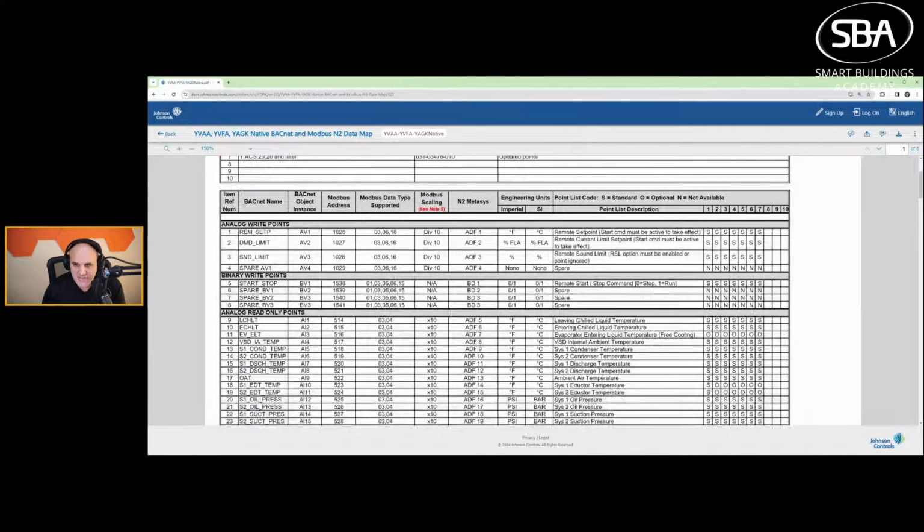This tells the chiller to turn on. But behind the scenes, the chiller itself has a flow sensor, and it has a pump that's most likely interlocked with the chiller. So when you tell the chiller, hey, you're in run mode, you're in start mode, which you can actually see, 0 is stop, 1 is run.